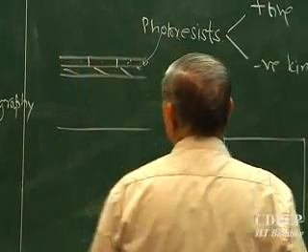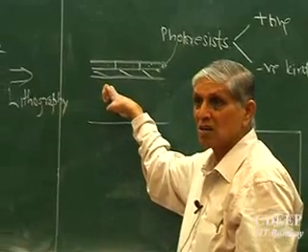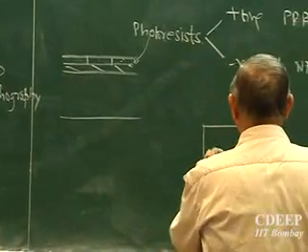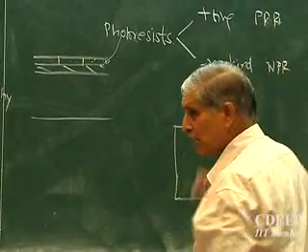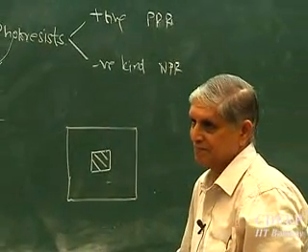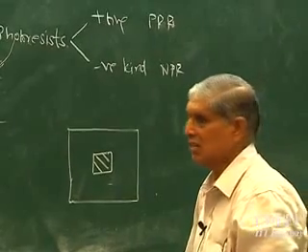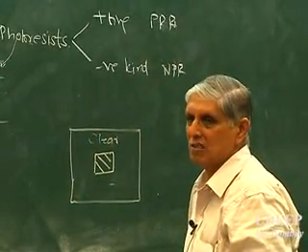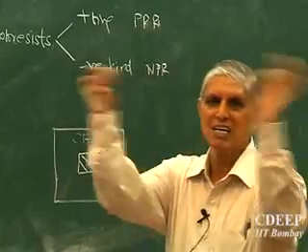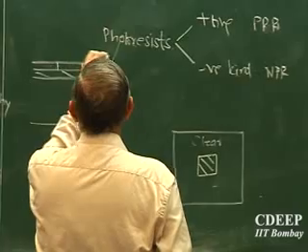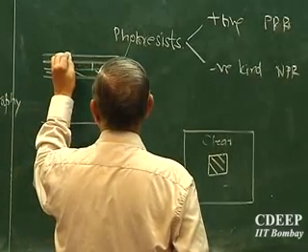So now, if I want to protect this much area, light should come on the rest of the part. Is that correct? Then the resist will become hard and nothing can be done there. So I put a mask, which is a glass plate coated with photoemulsion, in which this portion is dark. The rest of the portion is clear, transparent. This is called a clear field mask. Clear field means most of the area is clear, and only the area which you want to etch is dark.